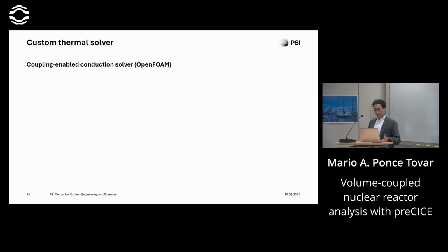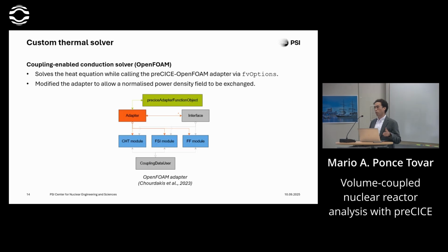And the thermal solver, as I mentioned, is just a very simple conduction solver. And it uses the OpenFOAM adapter directly with the one small variation that since the adapter basically expects only certain types of physical fields, I just added this generic power density field to the adapter.